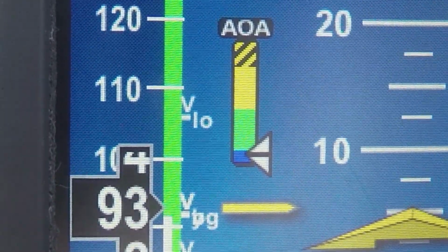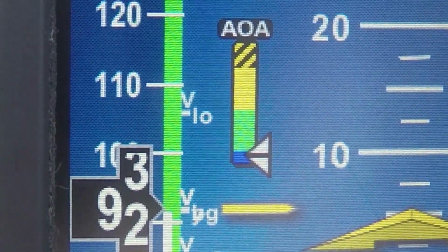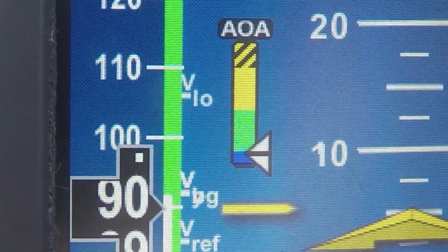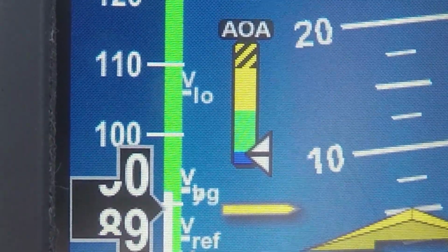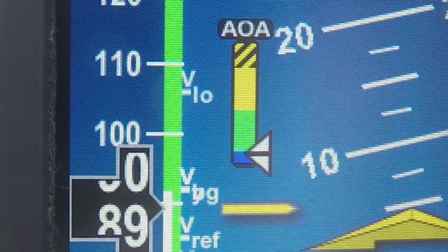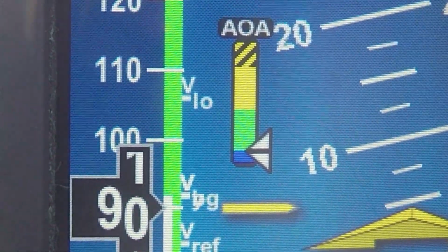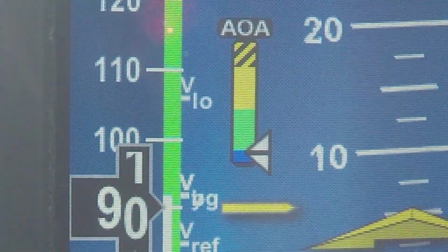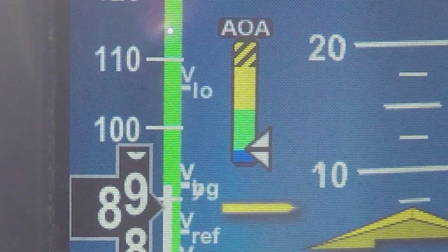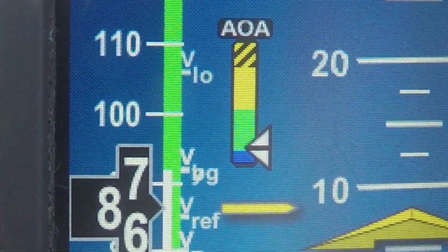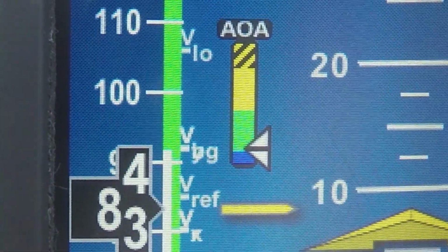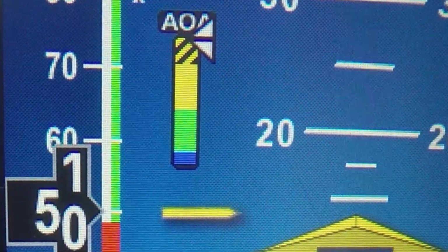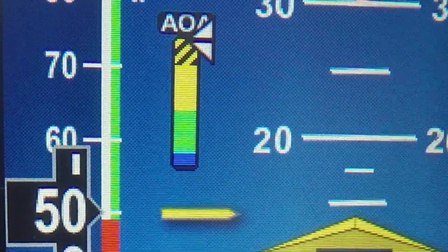It's simple, but it requires some explanation. The AOA scale range is expressed in a single vertical tape with 2 pointers. One is for flaps up AOA, and one is for flaps down. Here we've got the flaps up. In cruise flight, which we're in now, the pointer either fades away or drops down into the blue zone because the angle of attack is considered non-critical. As AOA increases, the pointer rises through the green toward the yellow and eventually into this crosshatch area, which indicates minimal margin against an impending stall. And here's what the full stall looks like and feels like.